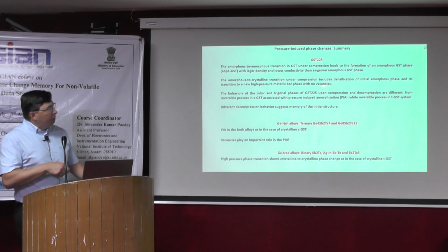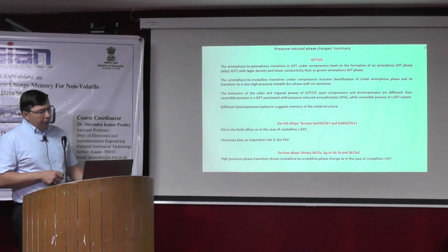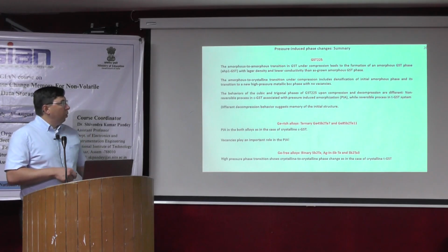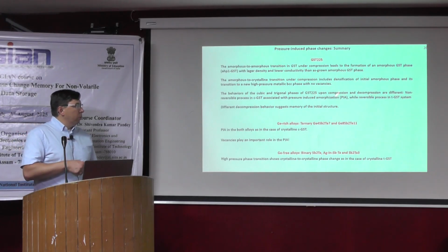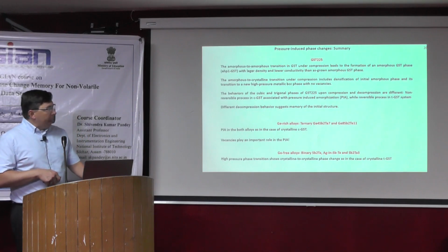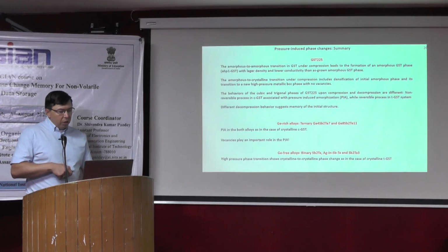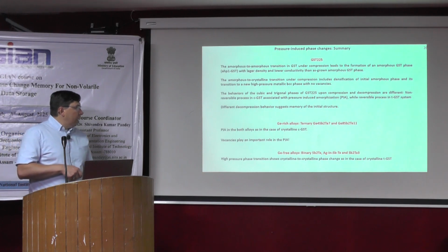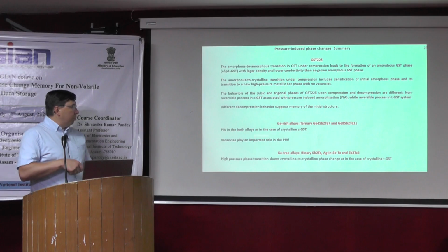We observed and discussed that the vacancies in these GST phases play a huge role in this phase transition. In the case of germanium-rich alloys, like ternary germanium 4 antimony 7 and germanium 8 antimony 11, there is pressure-induced amorphization in both cases, as in the crystalline CGST. As I said, the vacancies play an important role.